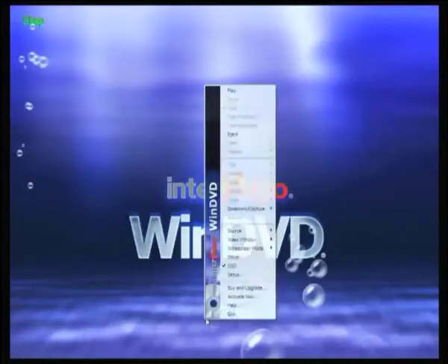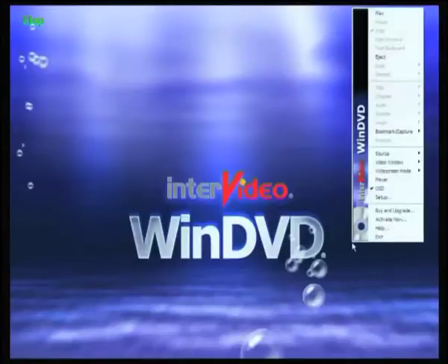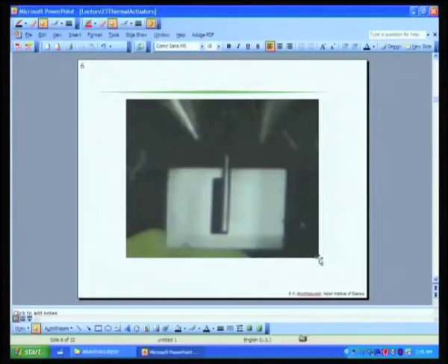Okay. You can actually see vaguely that it is getting hot, the redness can be seen, and by applying a lot more voltage you can actually melt it. So, you can go to very high temperatures in these up to the point of melting. You can clearly see it moving this way and that way. The force in this will be quite large as compared with, let us say, electrostatic actuation.